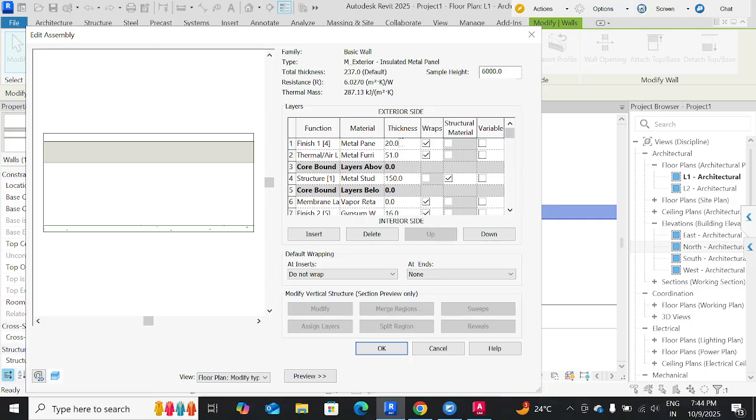If we use any option in layers, if we use anything here at 0 mm, just like a membrane layer, but still it is in the system, we should know that it's in there. Why do we have to put 1 mm, like you said before? You need to take a quantity takeoff. You want to take a schedule of how much paint you might require. For that, you need square feet.